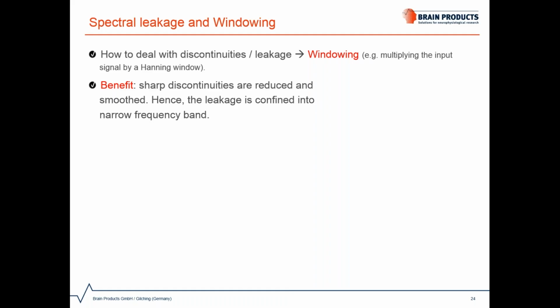Now, one might think, instead of being affected by spectral leakage, why not extract a signal of interest that results in an integer multiple of the frequency resolution? But unfortunately, it is not possible to know the frequency content of your signal of interest in order to match it with the frequency resolution. Had it been possible, we wouldn't be performing frequency analysis, right?